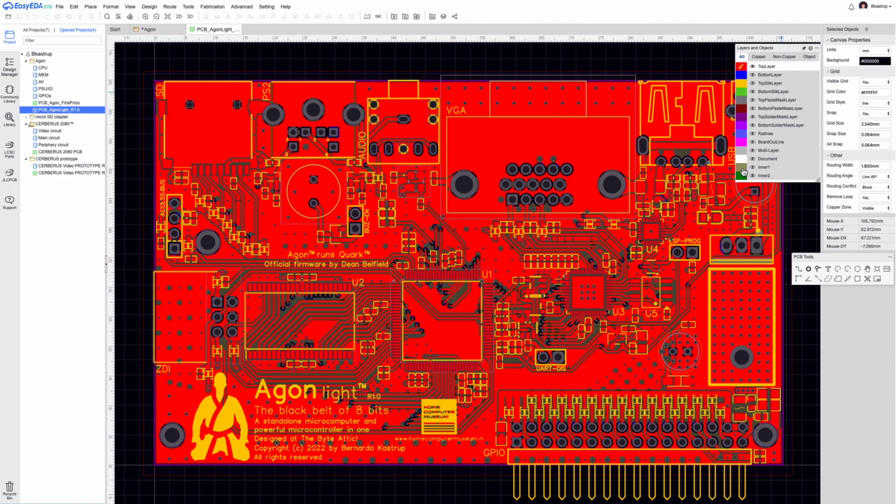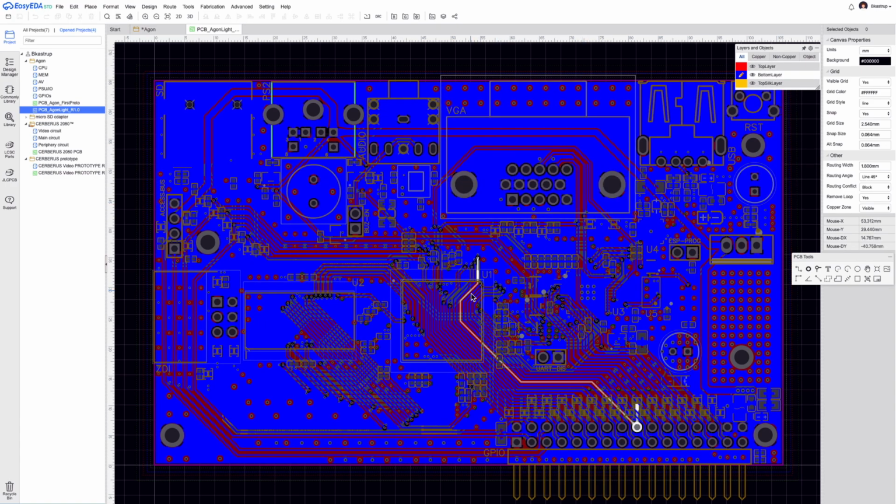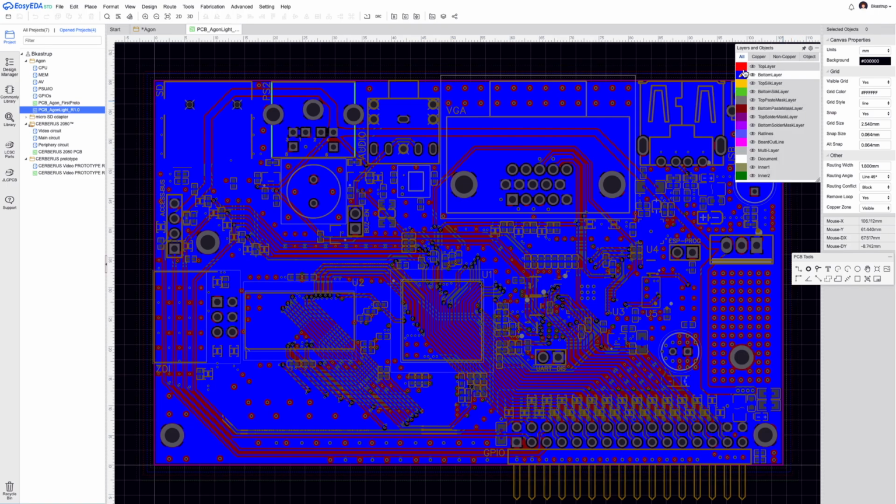So the electromagnetic field fringes couple vertically and not sideways, which would lead to crosstalk. And also to keep the bottom layer vertically as close as possible to inner 2, so that the EM field fringes of these traces here couple to the plane above as opposed to sideways to each other. So the larger the distance between the traces and the reference plane underneath or above, the worse will be the coupling between the signals on the traces and the reference plane, and the easier the signals will couple to each other, which is undesirable and leads to interference and bad-looking signals.